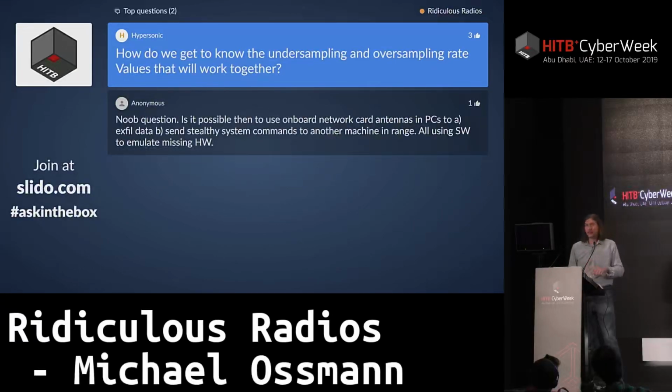Undersampling, traditionally, you have a sample rate that is higher than the frequency of interest that you're trying to capture. And in my example, I was capturing an intermediate frequency that was at 44 megahertz. And if I remember correctly, we were sampling at something like 20 megahertz.